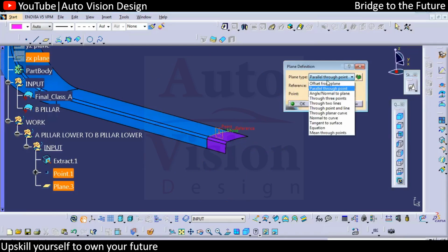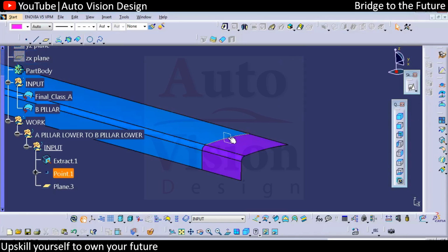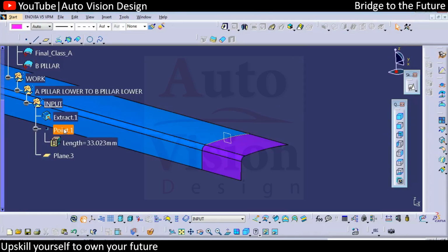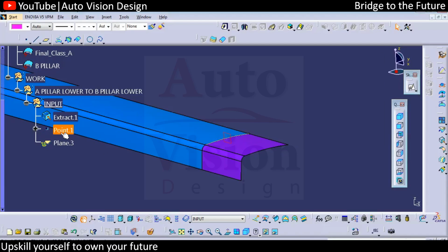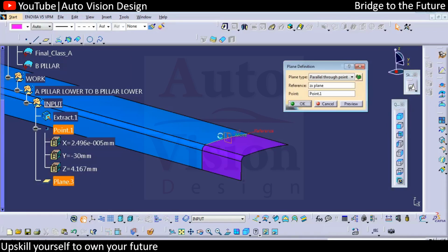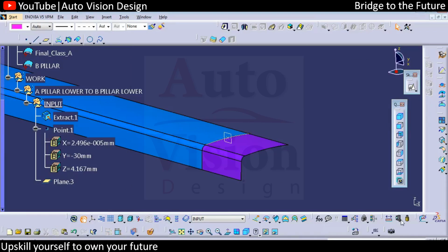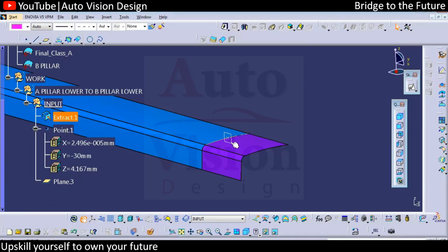You can double click and make it any coordinate. So you can just isolate this point, double click, coordinate. You can maintain this y value as over here is 30. Okay, so with y 30 you're going to get this plane. Now if you check the coordinate of this particular point or the section, you can mention that at y30 we have taken the master section.